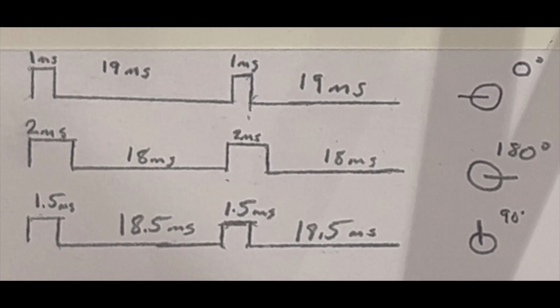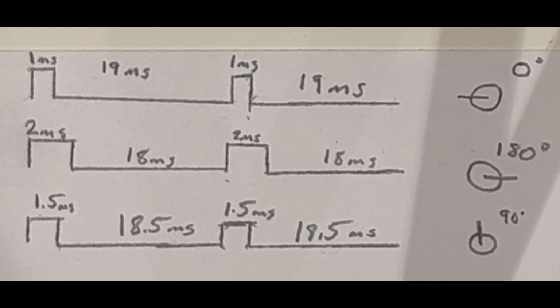The servos run off of pulse width modulation, or PWM. There's a method where we send quick electrical pulses to control the position of servo motors. In this project, the move servo function sends a high pulse lasting between 1000 and 2000 microseconds. The pulse width tells the servo where to move, and each cycle is 20 milliseconds in length.